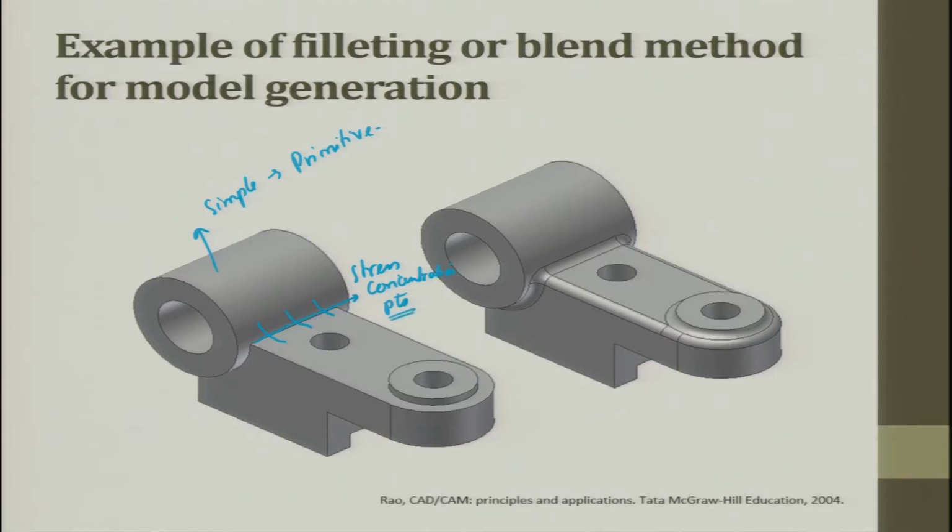and you can keep continuing this. If this is a flat one which just butts against a surface, then this will lead to a failure very fast. So, here we have an option of filleting. You can see wherever there is a sharp edge, there is an option of filleting. Filleting will enhance the safety as well as the life of the component. So, these are some of the examples wherein filleting or blending methods for model generation are possible.